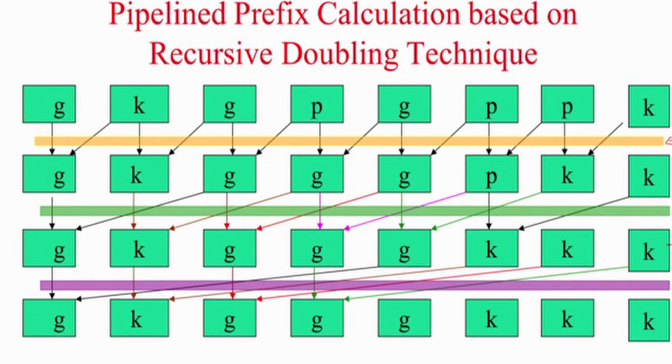So, the results are stored for computation by stage 2, and that result will get saved in the green register. When the first set of data is processed by stage 3, the second set of data can be processed by stage 2, and the third set of data can enter stage 1. The results will be stored in the respective pink, green and yellow registers at the next clock pulse. And again, when the first set of data is processed by S4, the second set can come to S3, the third set can come to S2 and the fourth set can come to S1. By this, I can keep adding numbers one after another very fast.